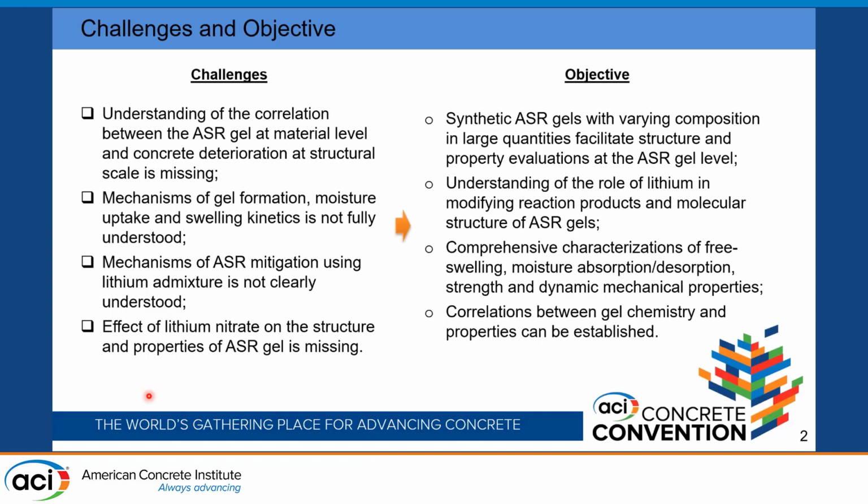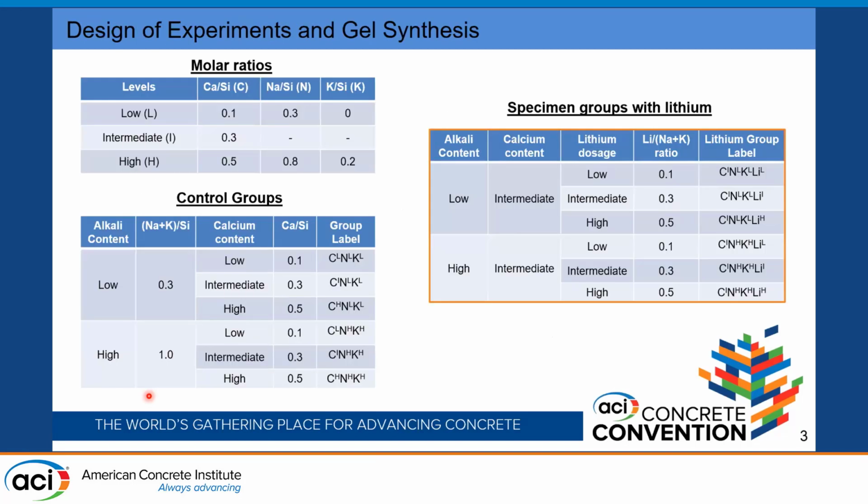We also aim to understand the role of lithium in modifying the reaction products and the molecular structure of ASR gels, as well as the comprehensive characterizations of freeze-thaw behavior, moisture absorption and desorption behavior, the developmental strengths, and dynamic mechanical properties. Based on all these results, we also analyze the correlations between gel chemistry and the properties.